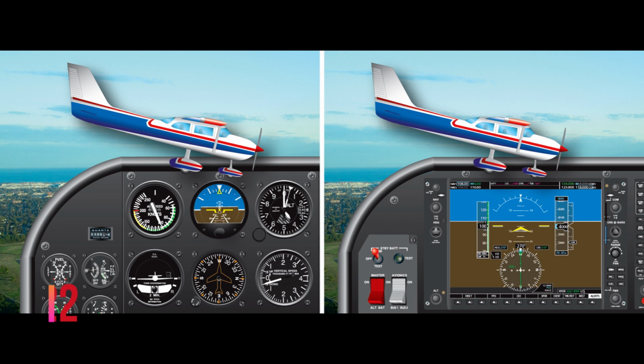Descents and descending turns. When an airplane enters a descent, its attitude changes from level flight to flight with a descent profile. Figure 3.22. In a descent, weight no longer acts solely perpendicular to the flight path. Since induced drag is decreased as lift is reduced in order to descend, excess thrust will provide higher airspeeds. The weight/gravity force is about the same. This causes an increase in total thrust, and a power reduction is required to balance the forces if airspeed is to be maintained.